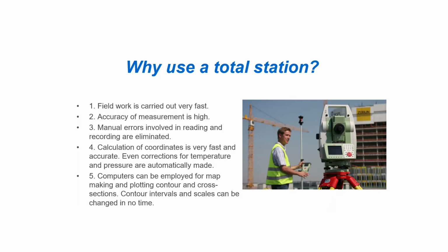We use total stations in field work because they are very fast. The second issue is that the accuracy of measurement is high. Manual errors involved in reading and recording are eliminated. Calculation of coordinates is very fast and accurate. Even corrections for temperature and pressure are automatically made.